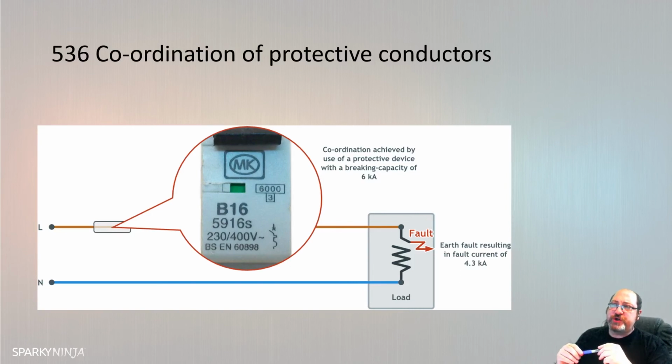If the issue was due to accumulation of protective conductor currents or an accumulation of gradual earth leakage, not a huge amount due to a fault condition, then likely the local RCD will operate first because that would be the one that would trip up that imbalance. But again, if they're 30 and 30, the one close to the origin would also potentially disconnect. So do make sure you understand how selectivity works with RCDs.